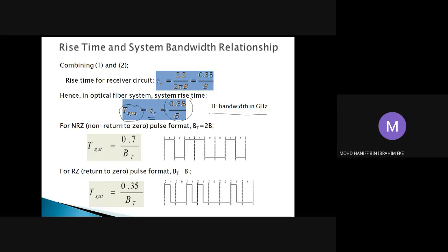Okay, so now for our digital case, because we are using fiber optics, for the modulation, for line coding, in order for us to send bits 1010 inside our fiber optic structure, normally we need to use what we call on-off keying. On-off keying can be divided into two types, where we have NRZ and also RZ. So these are two common methods of modulation for line coding.